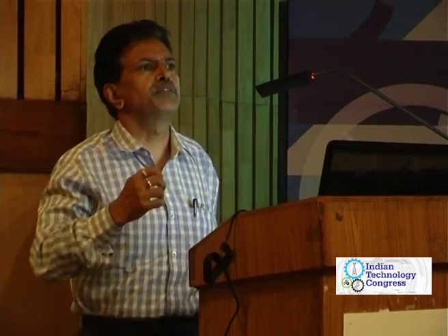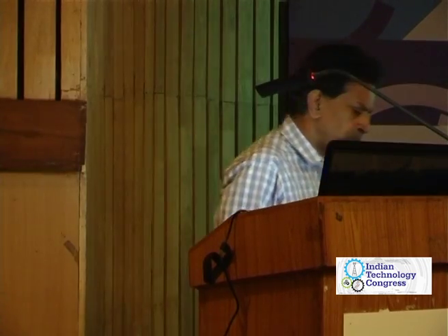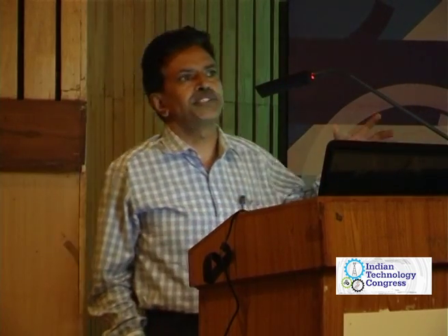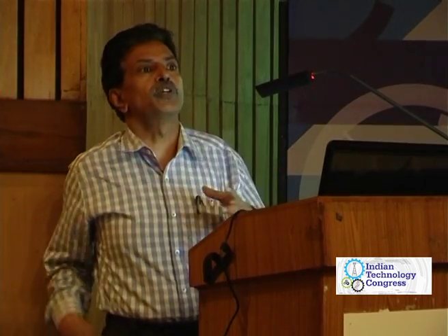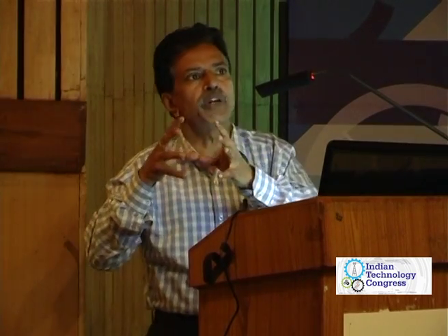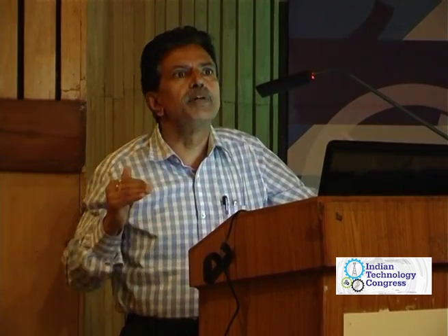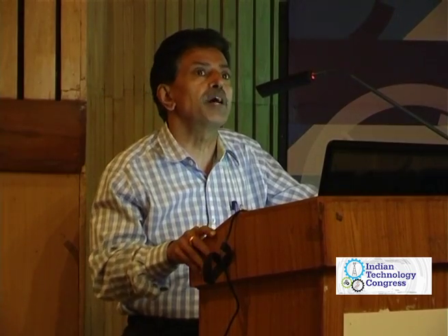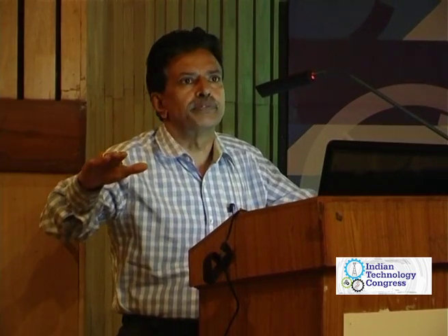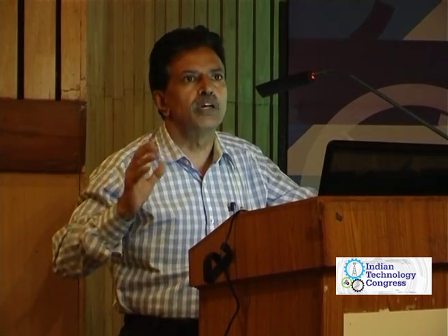Next is the processing. That's another major challenge when you're talking about a component. Again, with a piston, one day they were talking only about forging. Today people are talking about casting, then extrusion, and then forging, because they're talking about pressure tightness. That is very important for pressure tightness applications, so you need to ensure minimal defects. What we are talking about in metal matrix composites is, number one, agglomeration.